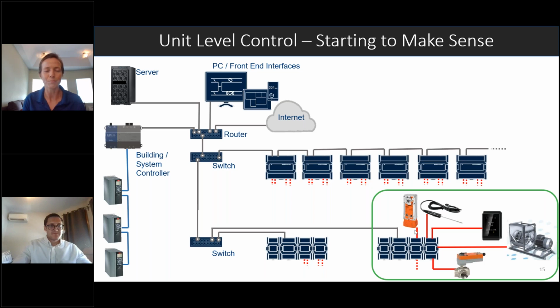But in terms of integration, I love a matrix of responsibility in the specification, because it can get sticky when you're dealing with another trade, such as lighting control, which is installed by the electrical contractor, as well as just doing your due diligence and making sure that that lighting control panel or gateway, you understand its capabilities. Are you able to only read certain points, or are there also read-write properties which give you control and command capabilities?